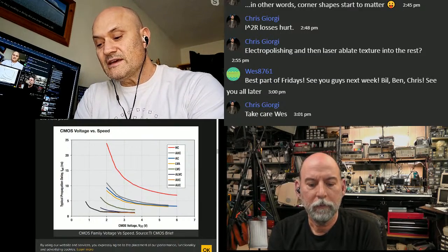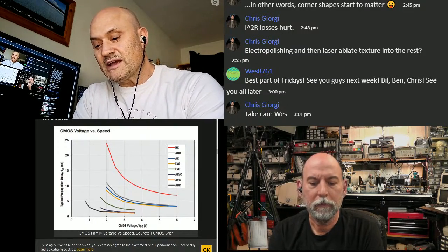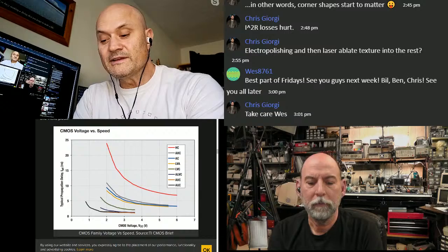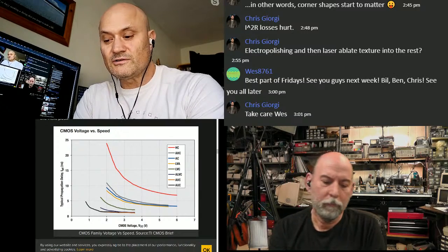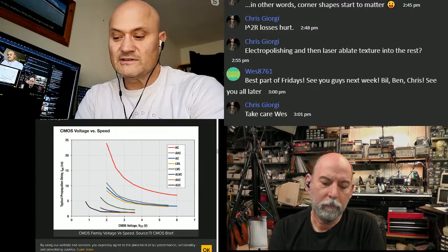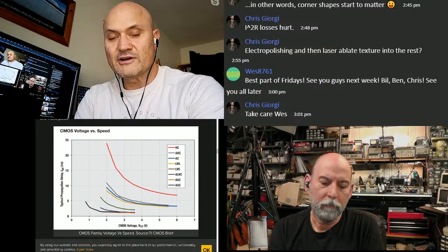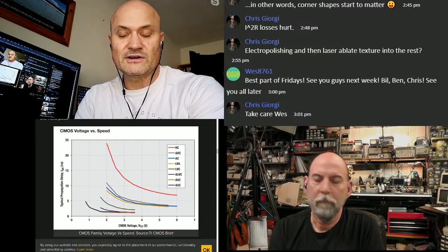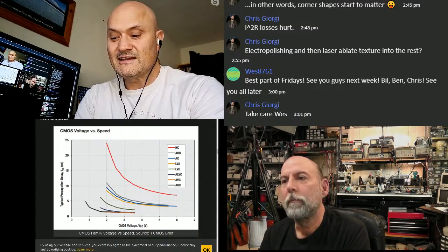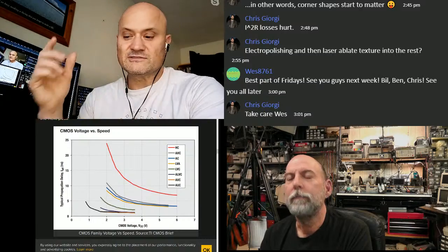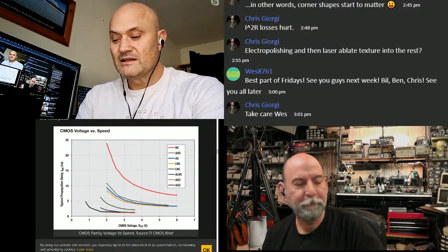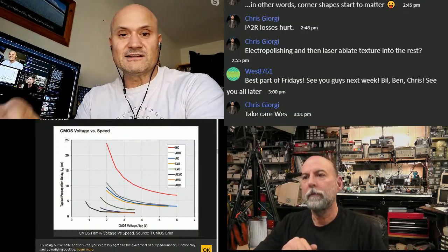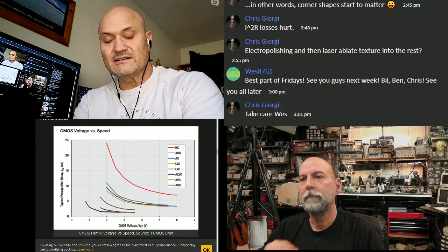Truth is, most fabricators do very common impedance control sort of setups. So they'll have 50 ohm single-ended, they'll have 100 ohm differential, 93 ohm differential, maybe 80, and various different things that come from other industry standards. Various compromises, yeah. Well, they come from standards like DDR, the JEDEC standard for DDR.